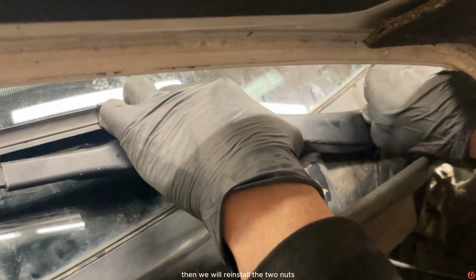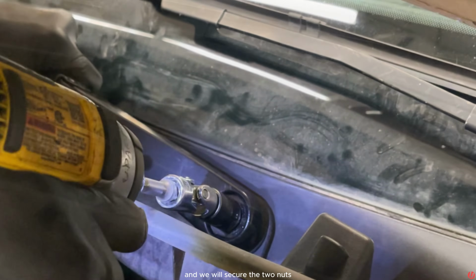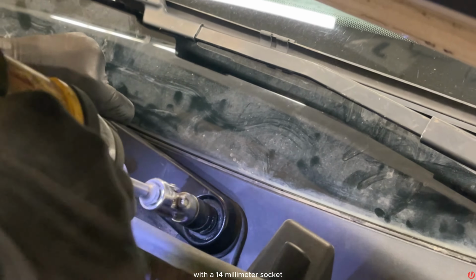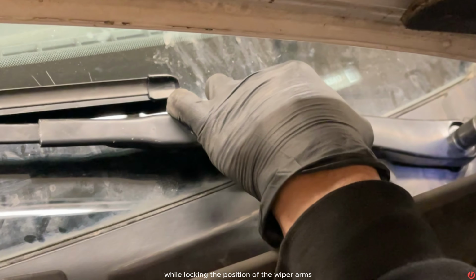Then, we will reinstall the 2 nuts that retain the 2 wiper arms in place. And we will secure the 2 nuts with a 14mm socket while locking the position of the wiper arms. Next, we will reinstall the 2 nuts cover cap on the 2 wiper arms.